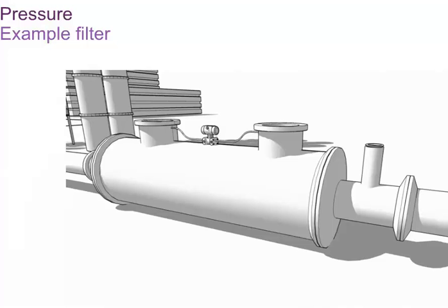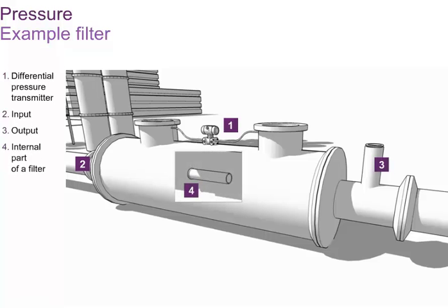Absolute pressure measurement at different levels of a column to achieve the right product and product quality in a refinery. Gauge pressure measurement at a compressor to protect the machine against cavitation pitting. Measurement of differential pressure between input and output of filters to recognize when the cleaning process has to be started.